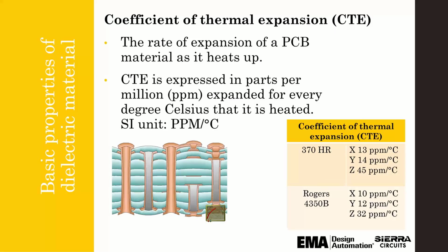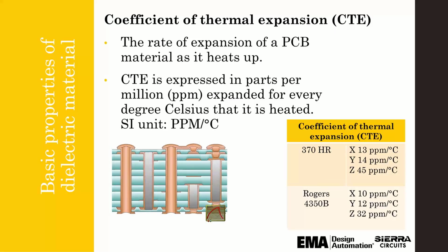And then last but not least important is the coefficient of thermal expansion. It's the rate of expansion of a PCB material as it heats up. And so this can be a very difficult situation if CTEs of different materials don't match up. The CTE of copper, the CTE of via fill material like a SANA or a silver fill, CTE of your component packaging and the solder joints, all that plays a role for the life of the product.